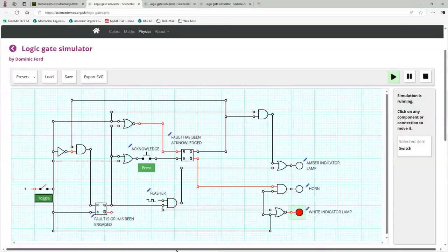So this is how I can use logic gates. And notice that, apart from simple gates, I'm also using SR latches. Now, in those sort of situations where you use logic gates, you need a latch. You need to have a stable condition. So without latches, you cannot create that circuit. You must use latches. Whether you use them this way, or create your latch using basic elements, it doesn't really matter. A latch is a latch.